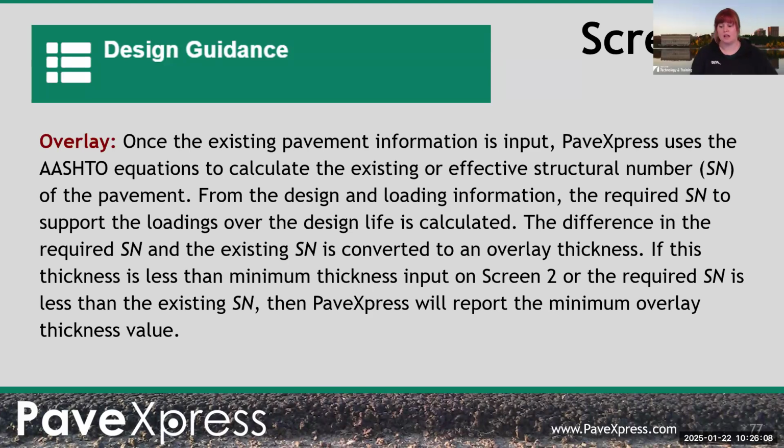So we've got a question: how would you add a crushed HMA layer? Is that bituminous treated base, or is that something else? If you're not really doing an overlay, if you're doing like a crush and shape, you're probably going to want to do that more in the new pavement design, I would say, because you're kind of obliterating that old road. Some of it you're using, the subgrade's still the same. If you had subbase or any base left underneath that, then you'd want to quantify that accordingly.